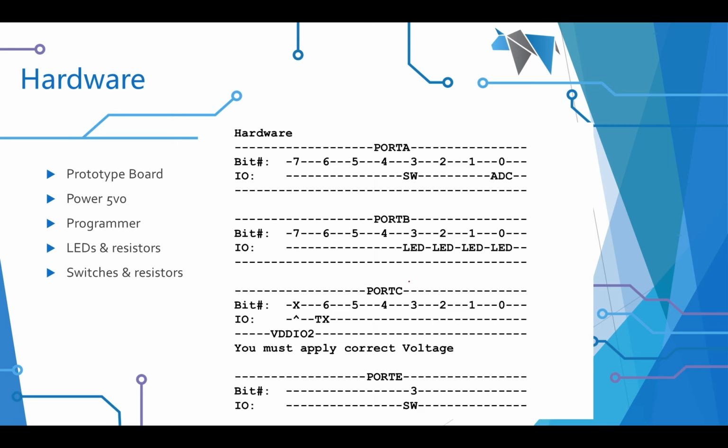I'm going to connect it on port C.6, and I put the TX in our little map. What's important about this is I had to choose it, and I'll show you how I chose that. You could put that on any of the valid ports. It's up to you where you put it, but I like it in that area there, so I've chosen port C.6.